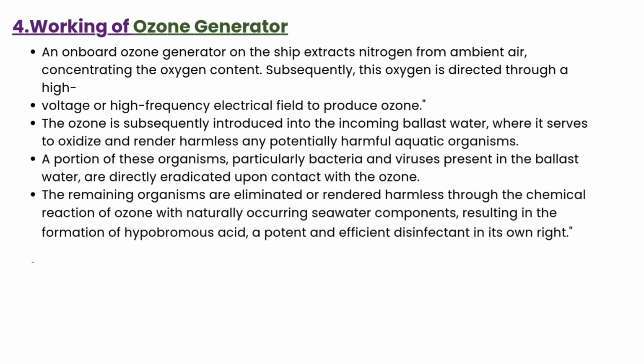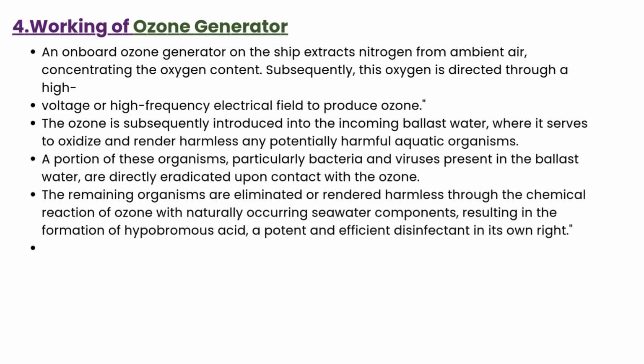The onboard ozone generator of the ship extracts nitrogen from the ambient air. We are using nitrogen also. This leaves a high concentration of oxygen. Subsequently, this oxygen is directed through a high voltage and high frequency electric field to produce ozone. The ozone is subsequently introduced into incoming ballast water where it serves to oxidize and render harmless any potentially harmful aquatic organisms. A portion of these organisms, particularly bacteria and viruses present in the ballast water, are directly eradicated upon contact with the ozone.